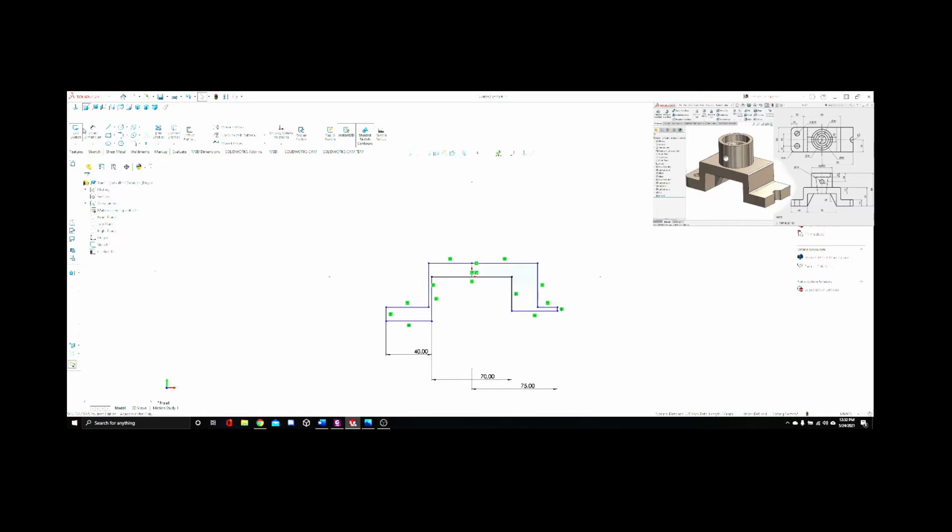All right. So we'll click on Smart Dimensions again. We know that our total distance across the top, from this point to this point, is 90, but we do this as two line segments. So we'll go up here and say this is 45, and we'll go up here and say this is 45. So that gives us 90 across. Now we're centered on this line as well on the top, and we know that the width of these bottom pieces is 15. Go there and say 15,